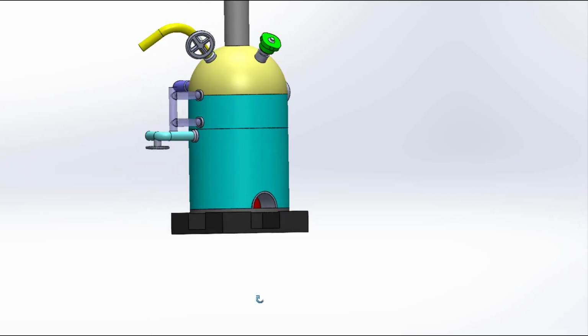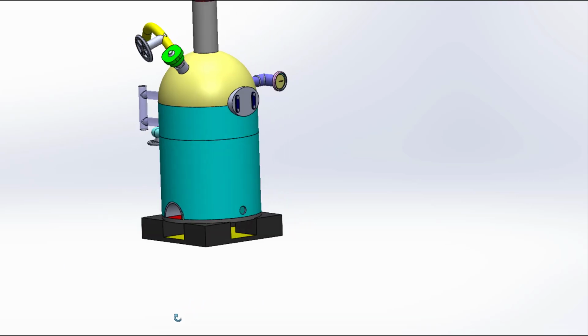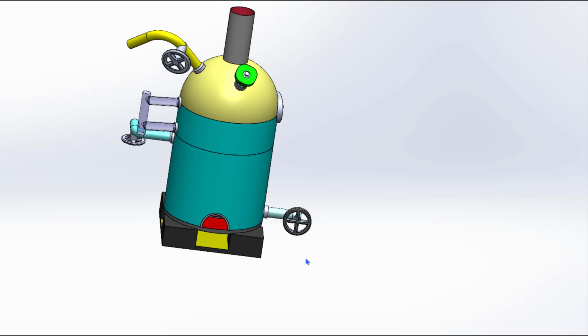A boiler continuously consumes water, and the boiler feed water may contain some mud or solid particles. Those muds will be deposited at the bottom part of the boiler because the solids are heavier than the water. So this is the most bottom part of the boiler. At this bottom part there should be one cock or arrangement, and if we open this cock or valve,